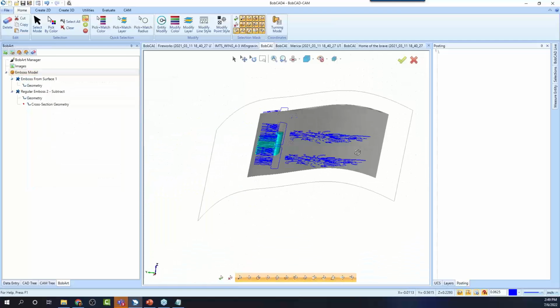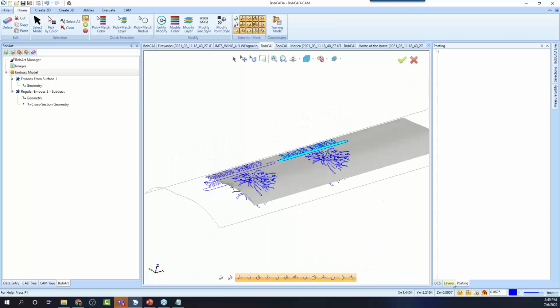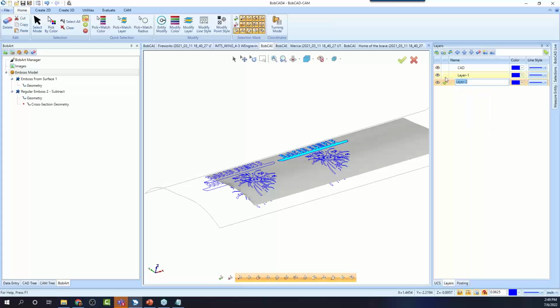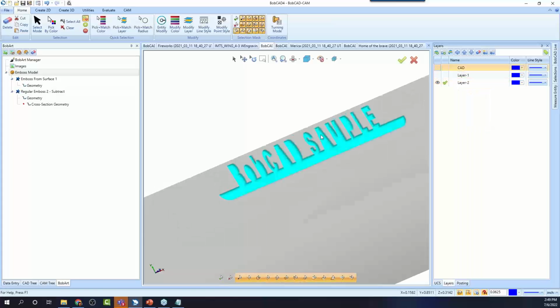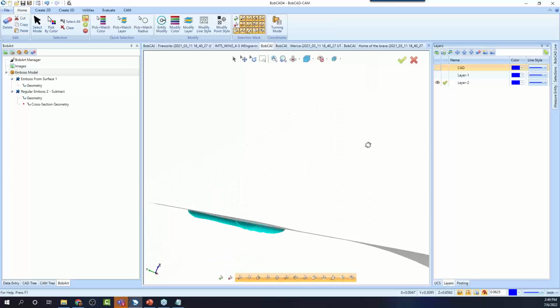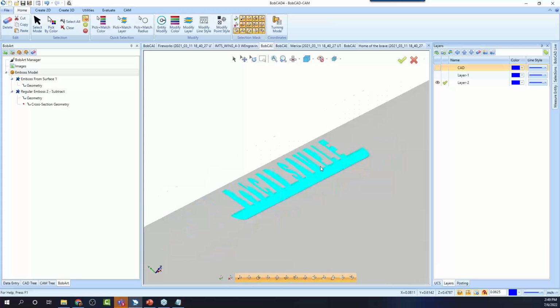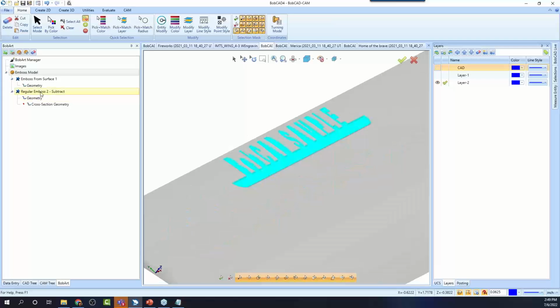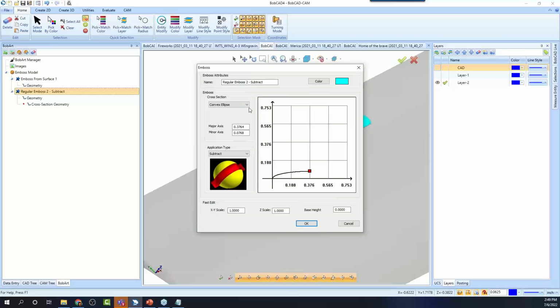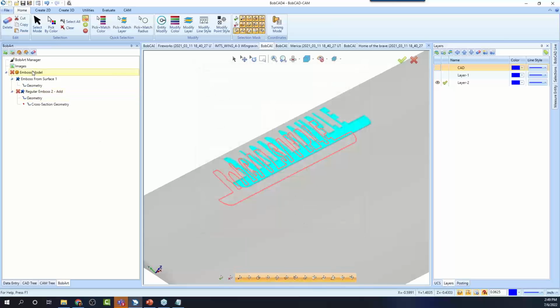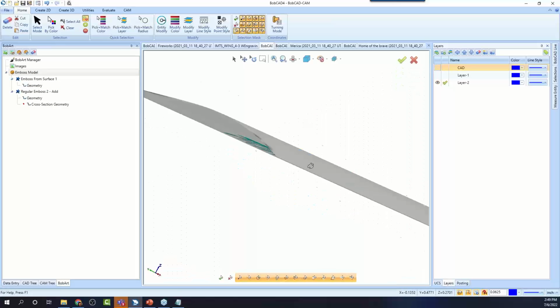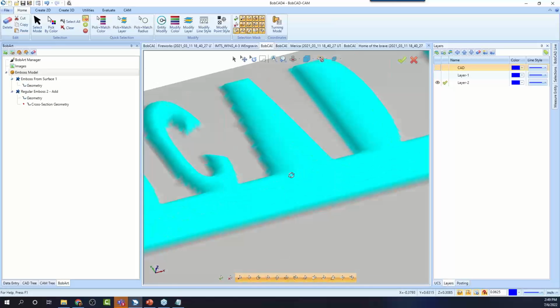And then now you can see how, I'm going to go to a new layer. I'm going to blank everything else out. Okay, so now you can see how we can put that along that surface. Now that can go down or you can have it go up, right? So we could say maybe instead of subtract, we can say add. Okay, come in and regenerate. And now you can see it's going up in Z.